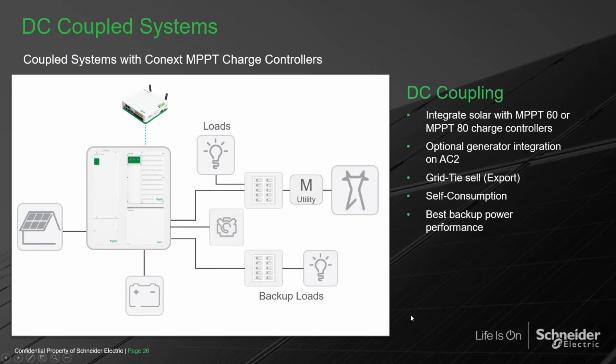Provided that I have excess power beyond supporting these loads, then we'll go here, main panel. Typically, we leave the larger loads out in the main panel. Things such as a dryer, or if you're cooking with electric, or if there are some large air conditioners, those are typically left on the main panel. So because this customer has a net metering agreement, the excess power will continue out, support these loads, and if I still have excess power, it will be exported out to the meter. Okay, so that's how the power will flow in a net metering agreement.